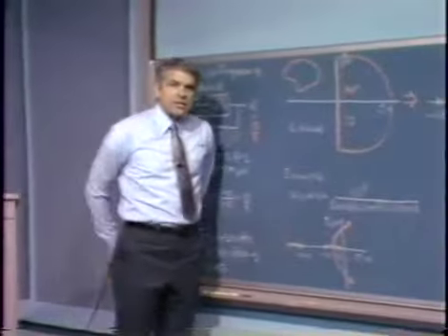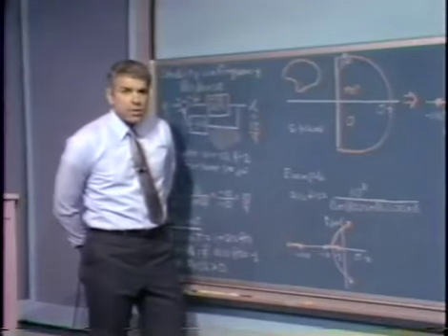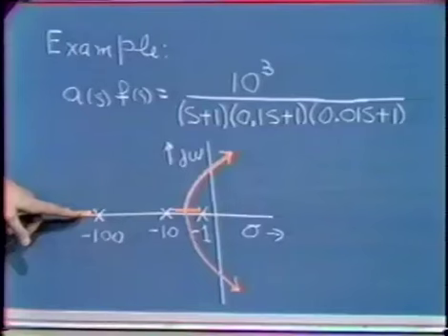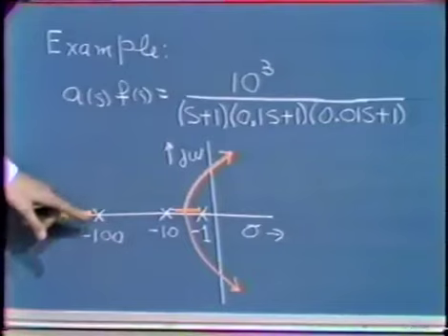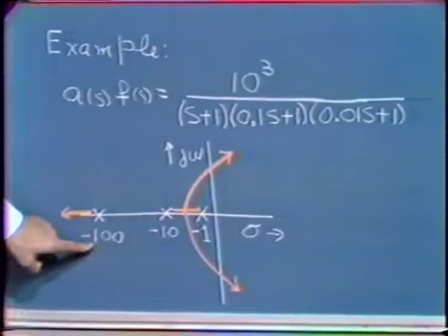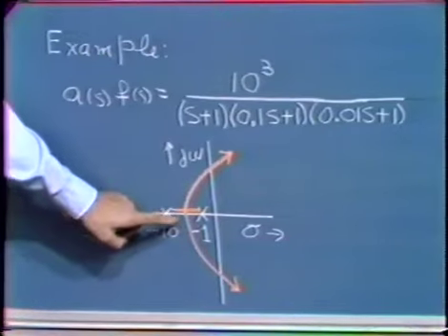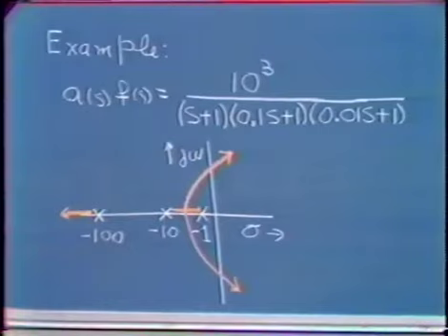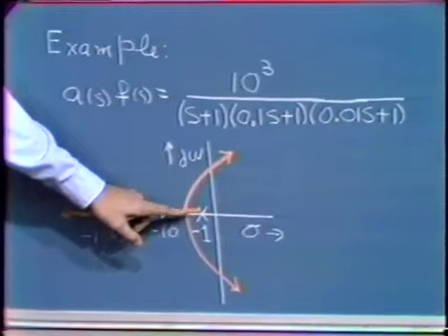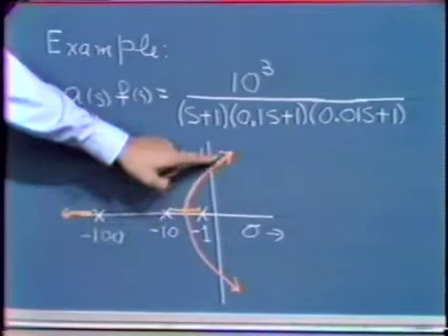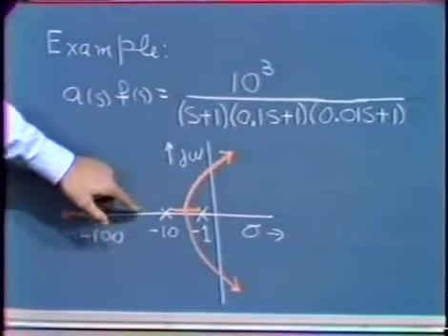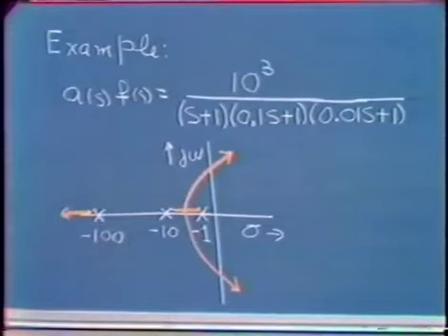We can get this same development by another technique that we know. We can look at this from a root locus point of view. And here we draw a root locus diagram for the same system. We have a pole at -1, a pole at -10, a pole at -100. And we find out that if we do the root locus construction, this is a familiar pattern. These two branches come together, meet at about the arithmetic mean, somewhere around -5.5, and then branch off, eventually reaching asymptotes that make angles of plus and minus 60 degrees. And a third branch goes off into the left half plane.